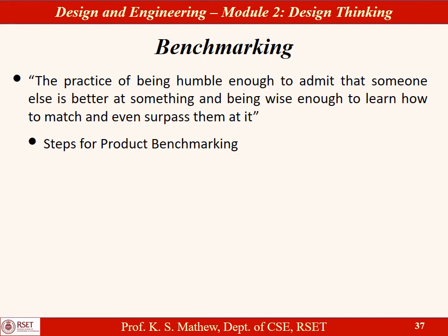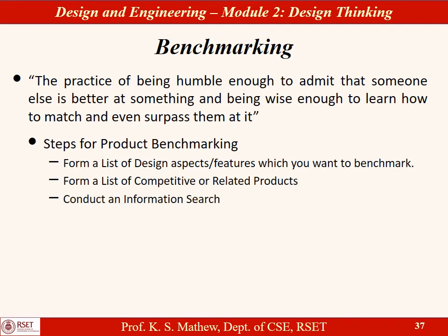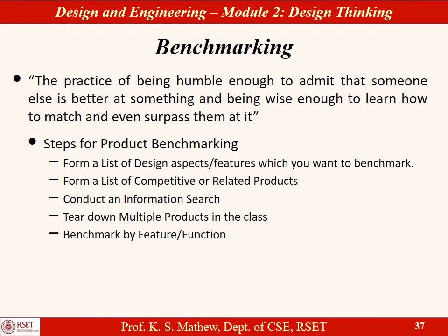These are the steps for product benchmarking. Form a list of design aspects or features which you want to benchmark. Form a list of competitive related products to which you are going to benchmark. Conduct an information search of the existing products in the market. Tear down the multiple products in the class. You try to decompose the product so that you can go into the details of each and every product. And benchmark for feature. You compare each of these features